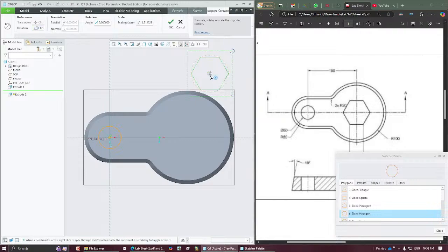If you left click and drag on that, you can put it wherever you want. I want to place it on the center of this. So you just have to touch that circle once, and when you get the circle, you just have to snap to that point. Once it is placed correctly, you just click the mid mouse button.